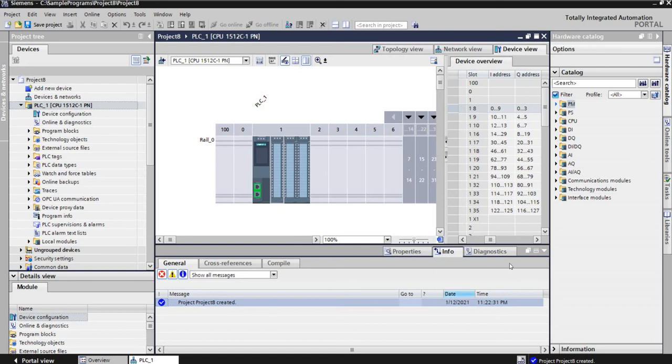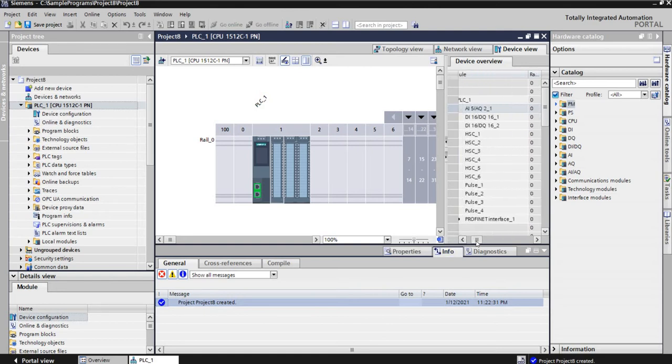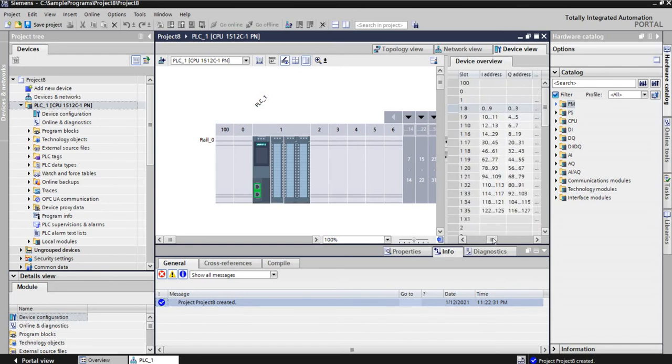This is very important for us in class because if you don't change that and you try to run your program, it's not going to work right, and you're going to be like, I did everything like you said. Your program's going to look really good and really right, except you didn't tell it the right PLC I/O addresses. The analog is using the addresses that we want. We want to use 0 and 1 for our digitals, but it's stolen by the analog right now. So we're going to give the analog just a random tag. I'm going to use like 126.